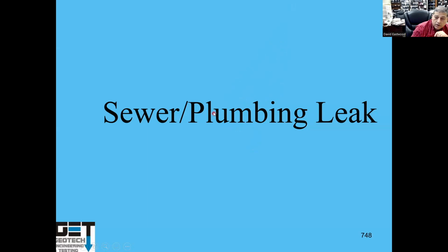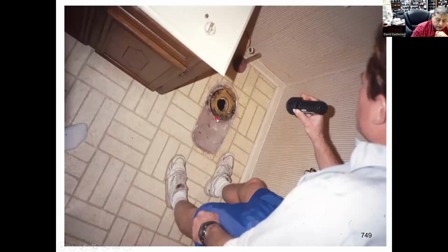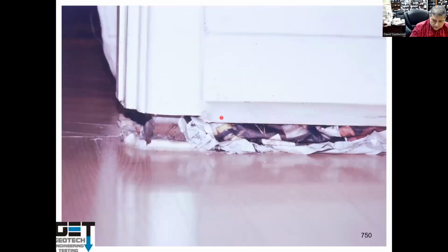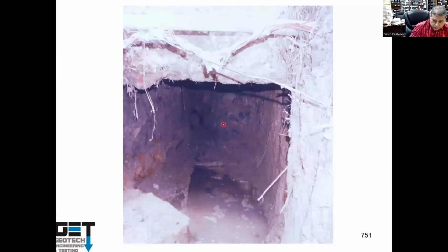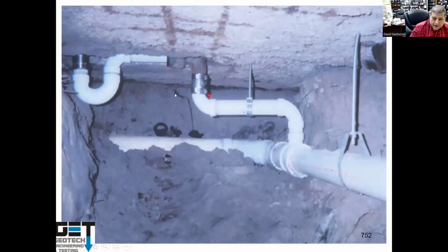Sewer leak, plumbing leak on the older buildings where you got plumbing problems, when you got a leak, even on the new buildings. I'm looking at some buildings out there near Dallas right now. They put the plumbing inside the expansive soils, heaving and pushing all the P-traps up and busting all the plumbing. And there's a leak. If there's a leak, it causes foundation movement. This is a leak due to plumbing, wetting the soils. You got to put new plumbing in.